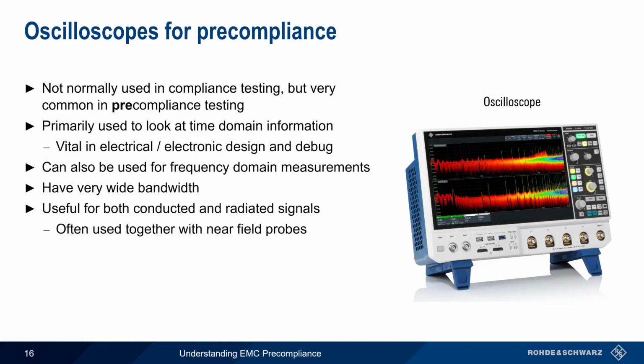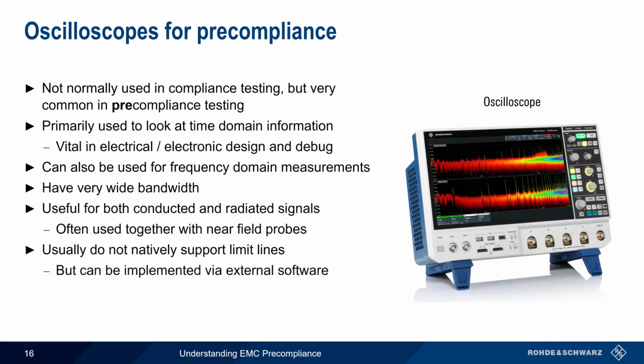One drawback of using oscilloscopes for pre-compliance testing is they usually don't natively support the limit lines that we looked at earlier in this presentation, although limit lines and other EMI-related features can sometimes be implemented using an external software program that obtains and processes data from the oscilloscope.